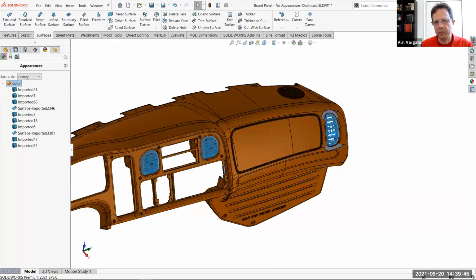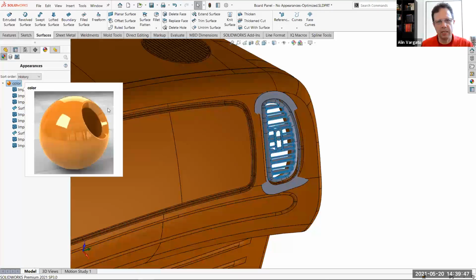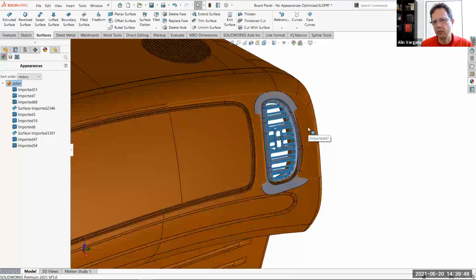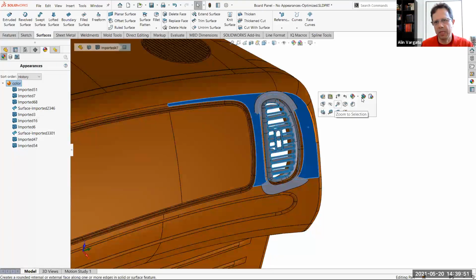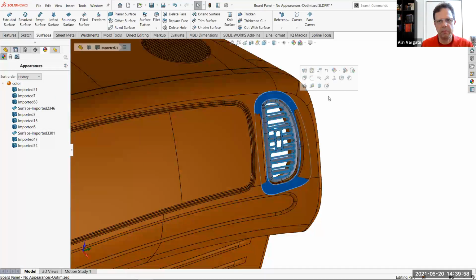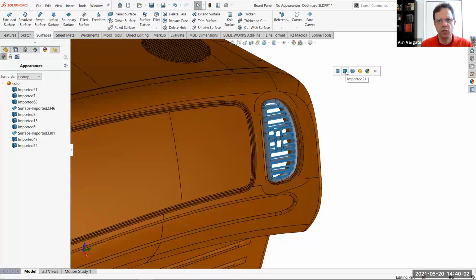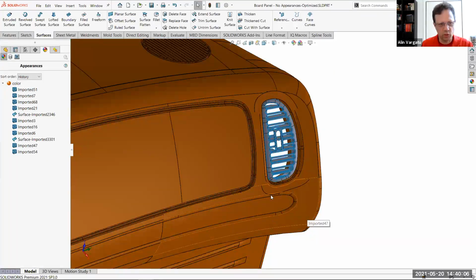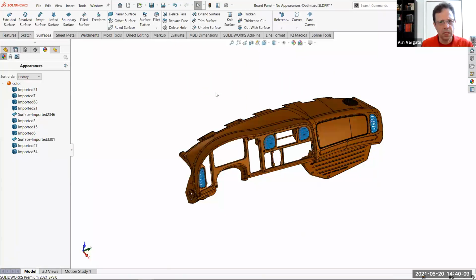The other tip that I can give you is that if you want to apply this color to other features, another way to do it is to simply copy the appearance from one of the faces into the memory and apply it by pasting that to the feature level. You can see I'm adding one more feature to that list. Good, we did that, right? Now let's click on the orange color. Let's see what happens.